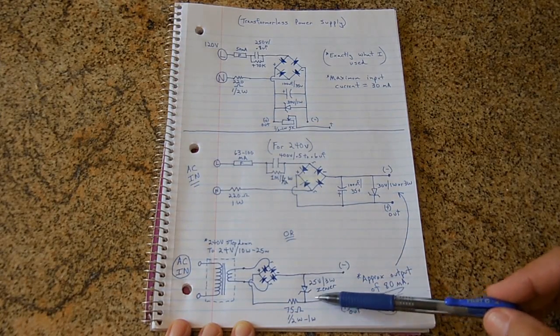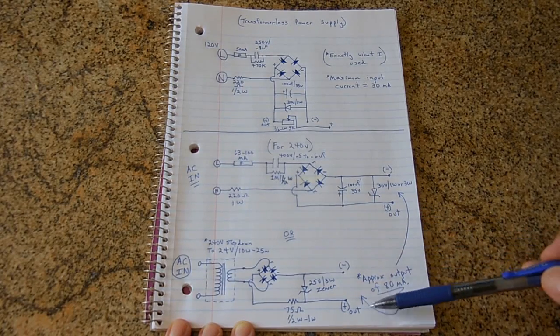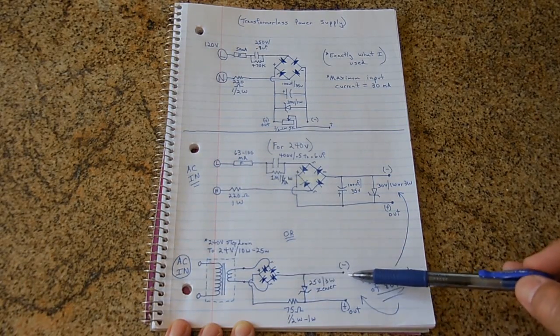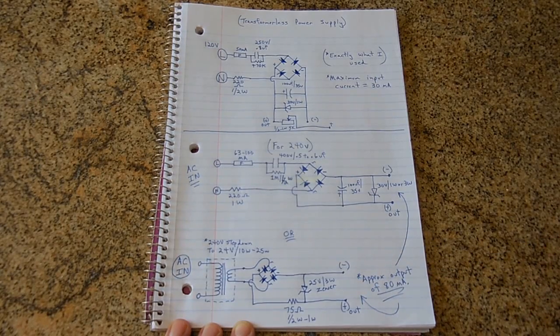Cathode connects to the resistor and to the positive output, which is 25 volts, going to the location on the flat ribbon where I showed you the soldered areas. And the anode goes to the negative and over to the negative area of the strip where I showed you where the solder is, pins 7 through 10.